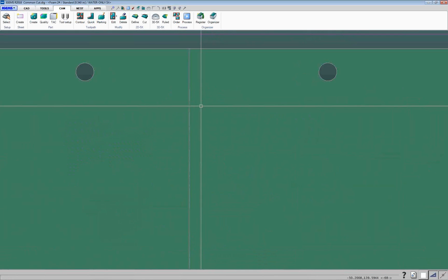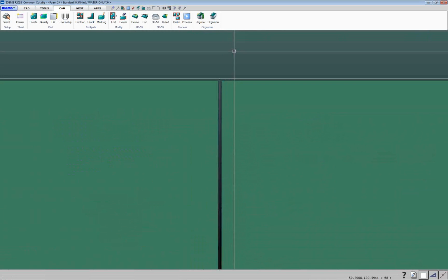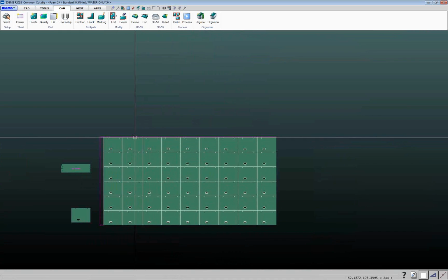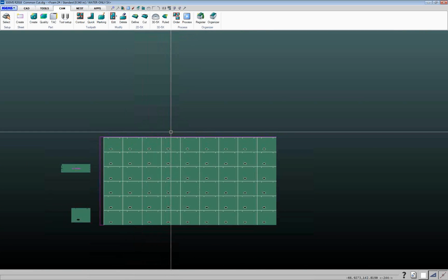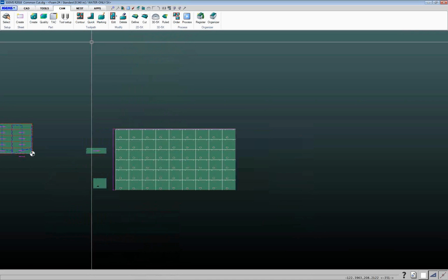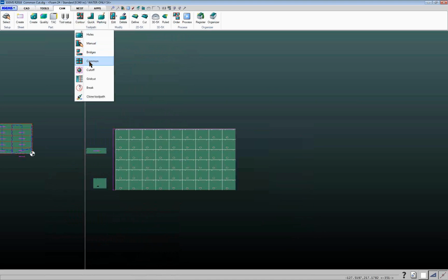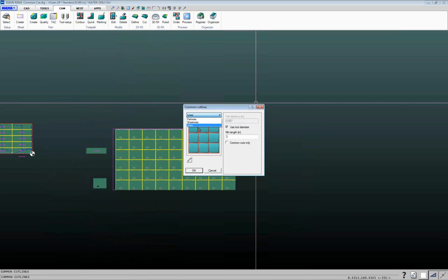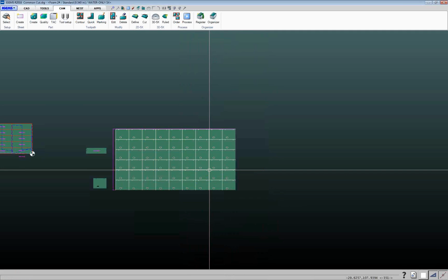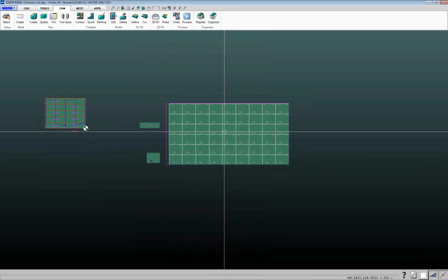So basically what it did there was, rather than creating a tool path, it just makes the CAD lines for that common tool path. And then, as I say, you could copy that, make a DXF file if you want to bring it into another CAD package. So I haven't really found a lot of use for that myself, but that is available. That's what that lines option is there for. So that's the common cut command.